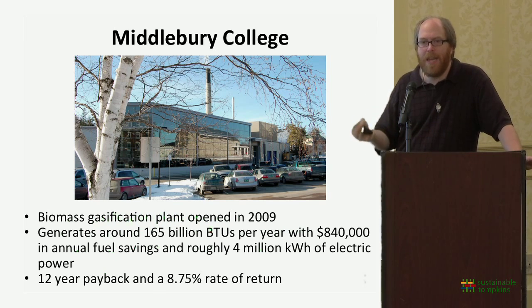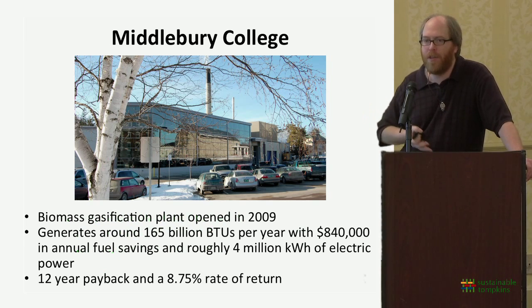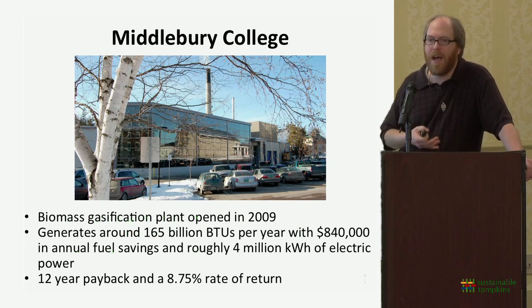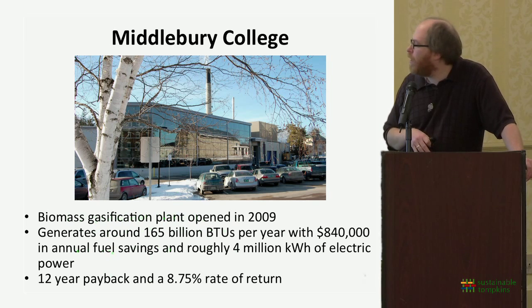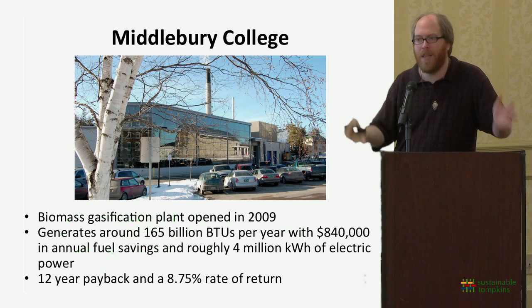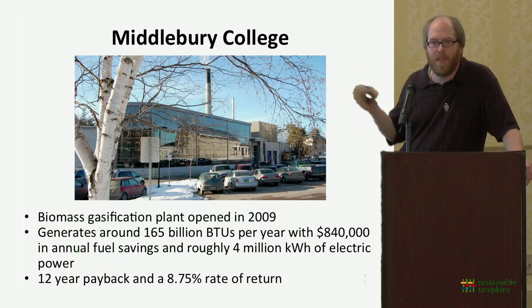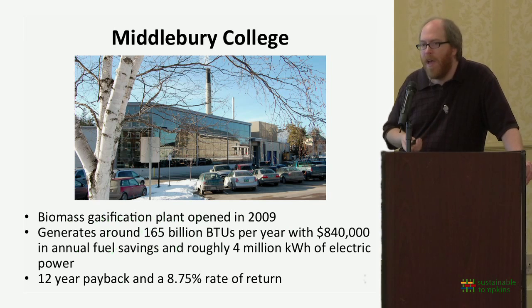One of the things you need when you're going to have combined heat and power is a relatively high electric demand that goes with your relatively high heat loads in our particular climate. And so, for instance, when Cortland looked at this, the balance between our heat demand and our electric demand was not such that this looked terribly attractive. For others, this will look very attractive.